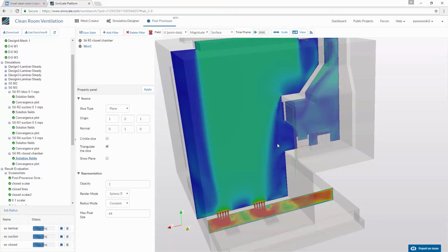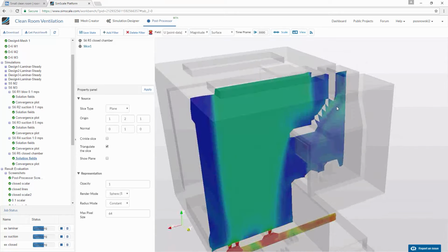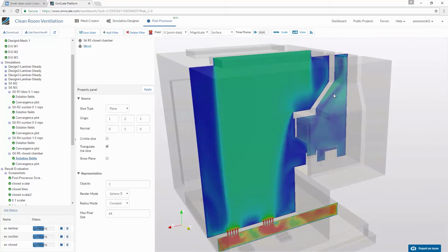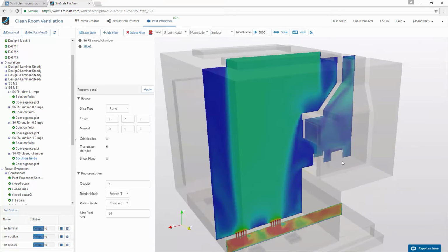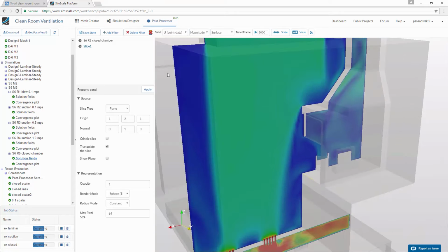And as expected, since we closed the chamber, most of the flow comes from the inlets, enters through the open boundaries at the bottom, and flows out. At the same time, there's quite a lot of recirculation going on within our reaction chamber, simply induced by the inlets coming from our pots. They have to exit somewhere, and they are driving the flow.